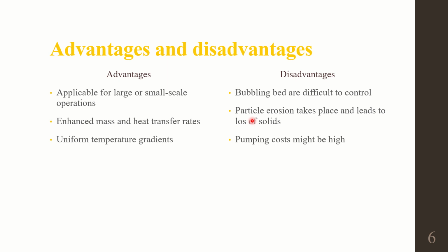And third is pumping cost might be very high. Since we are passing the fluid inside the bed, depending on the pressure drop of the beds, the pumping cost would be varying. So the proper design of the fluidized bed is essential. Otherwise, the pressure drop would be very high inside the bed, thereby leading to higher pumping costs. So therefore, it should also be taken into account when we are designing the fluidized bed. But in general, that is one disadvantage.